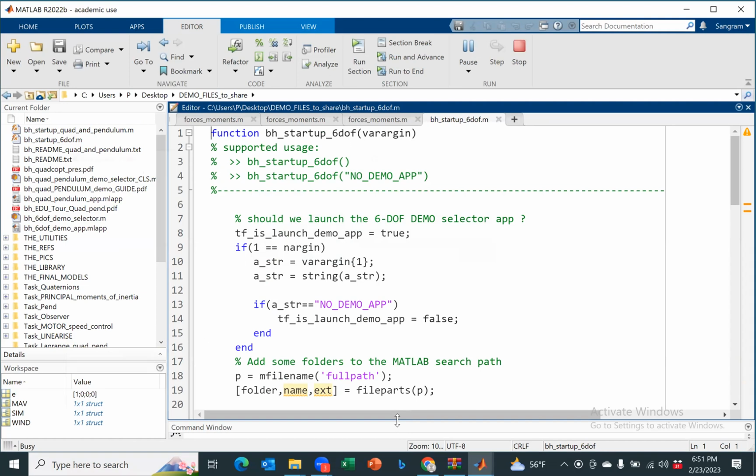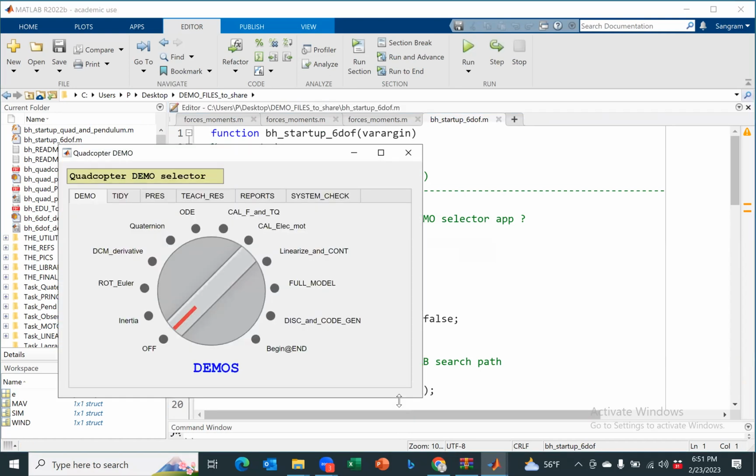And it's a huge, it's about, and then here comes the knob. Now, what I want to show you is, this is the template. This is the template for designing the control for any flight vehicle. If you want to do it, you start with the inertial properties. Then you look at the rotational matrices. Then you look at the Euler, depending upon what type of formulation you want to use.